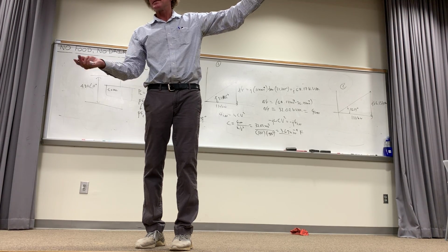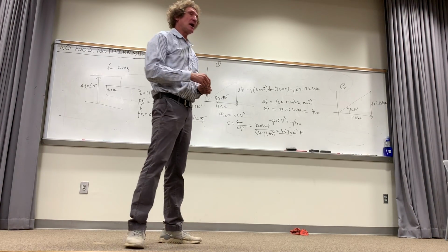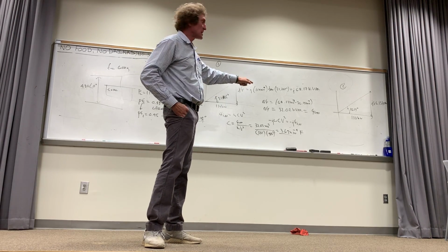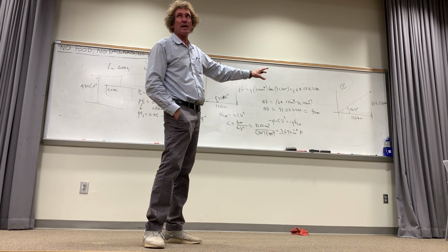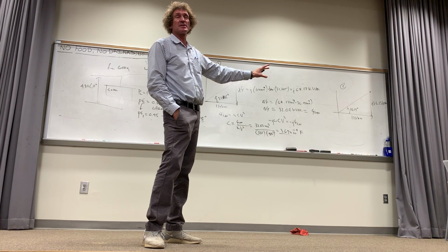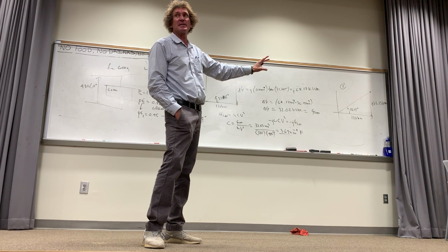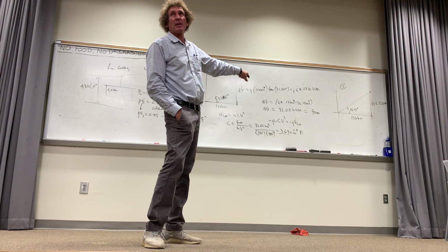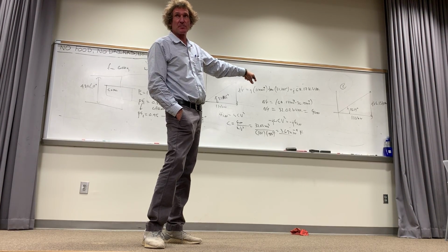But everybody benefits. I have to tell you one last thing about these capacitors. These things have to be at the line voltage of 480. They have to have a breakdown strength of at least that, typically about 10 times that, because you get transients. That's an expensive capacitor. That's a very large, expensive capacitor.